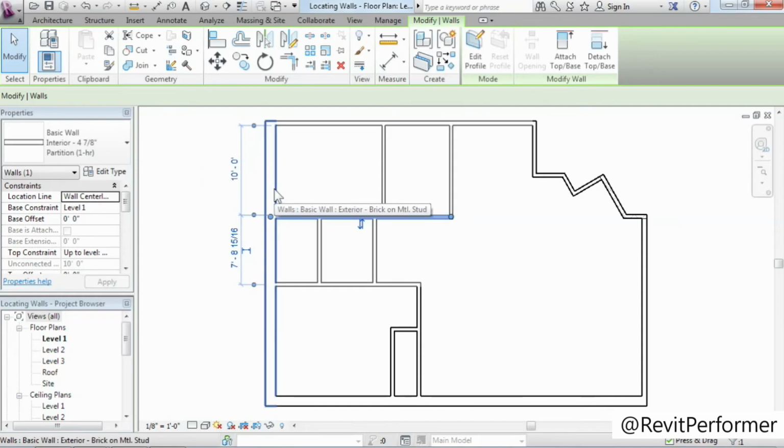Now here's a very common mistake that a lot of folks will make. They now want to set the size of this closet here, and so they immediately go to this dimension and put in their new number. But what you'll notice is the same wall that I had selected just moved and actually messed up the number that I previously typed.